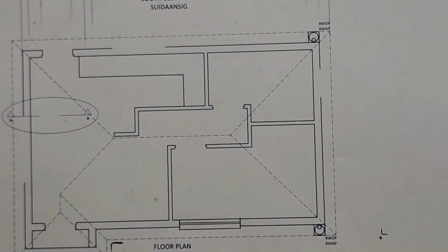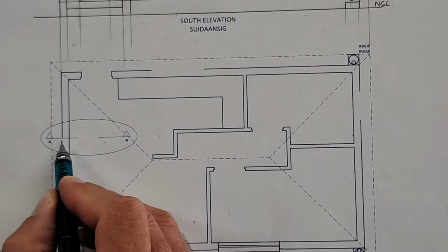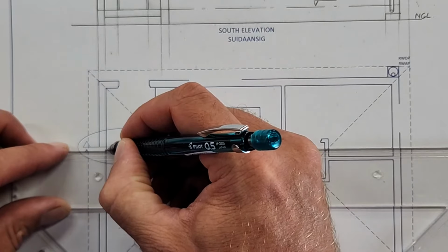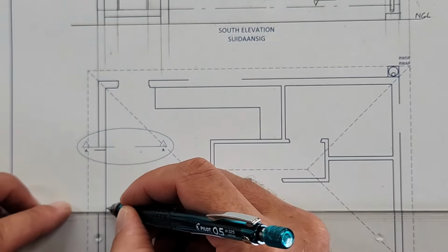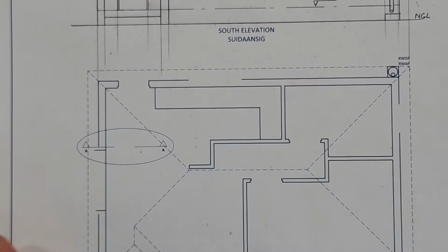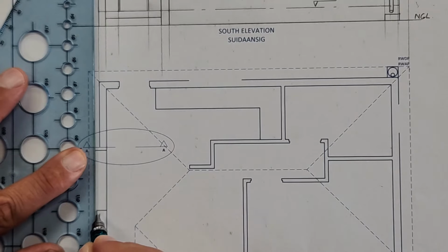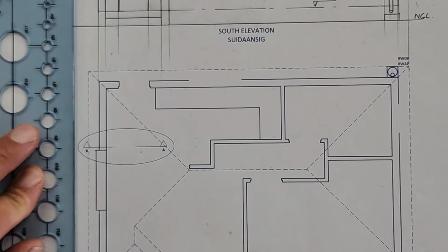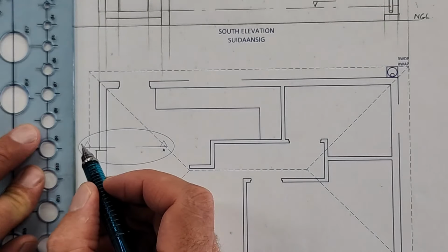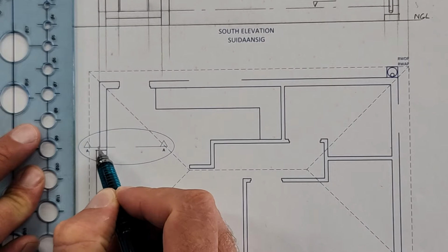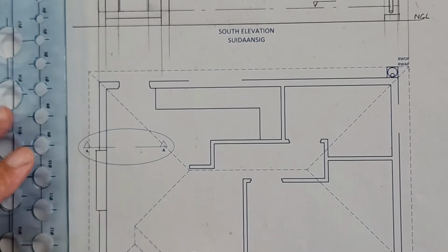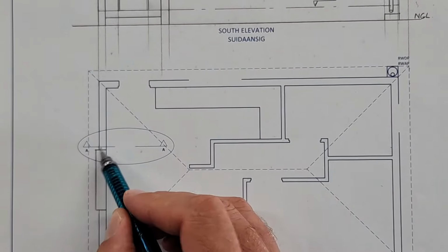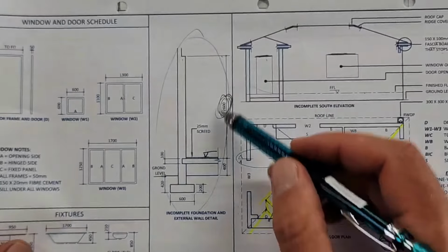Look at this one. This is so good. When I draw the window, look at where this cutting plane is. If I do my window correctly, I'm going to actually draw my window in here. So is this cutting through the window or the wall? You see? But the child that doesn't realize that is going to cut the window. You waste time and you're going to lose marks. So look at that cutting plane. Exactly, it's actually cutting through the wall. Okay? And there's all the information.